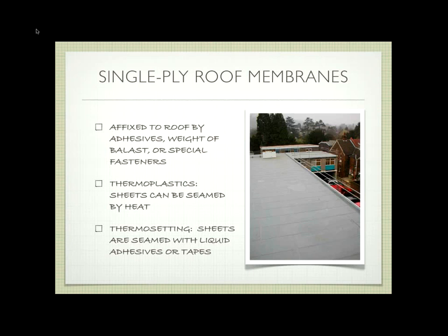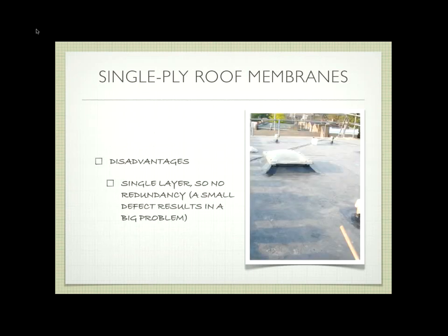Generally, if you're working with that kind of material, it does require a special roofing contractor who's certified to work with that particular material. So you have to be aware of that. Okay, so again, if it's just a single layer and you have one accidental nail that pokes through it, you now have a leak. So there's no redundancy: if something scratches the top surface and water gets through, there's no other layer underneath that blocks it. That's the one thing you're giving up, okay?